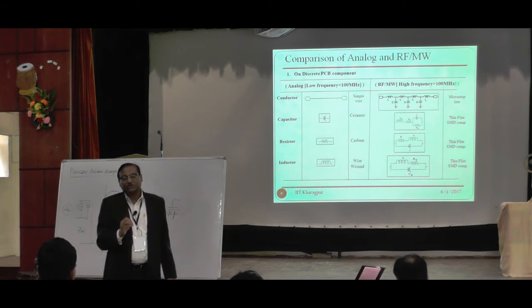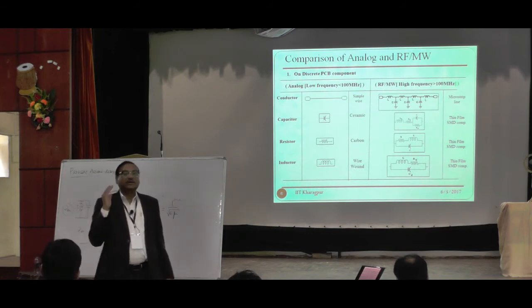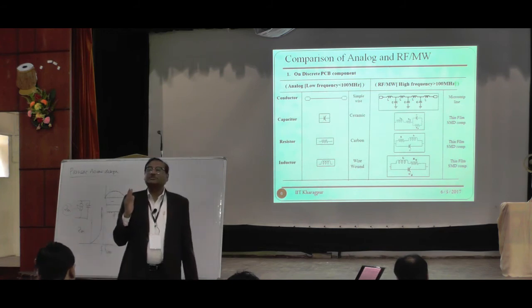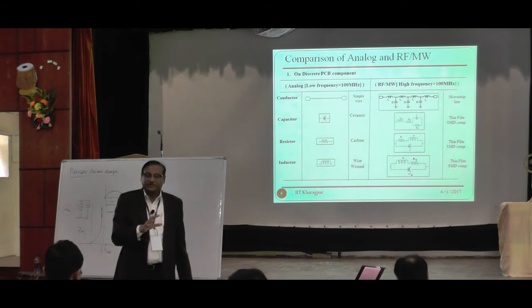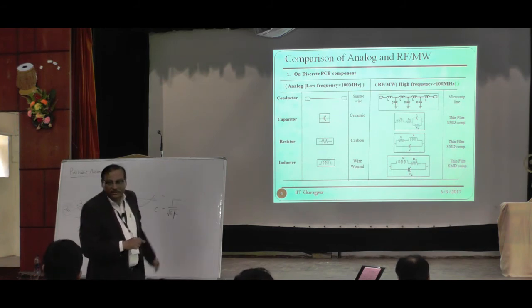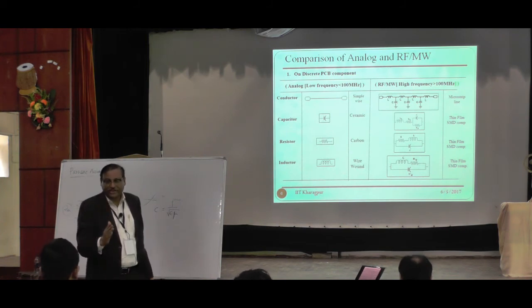You have to find out what is, in case of transistor, what I said, the cutoff frequency. Cutoff frequency means the frequency of unity gain bandwidth. And the self-resonance frequency, just as explained. So those frequencies are the limiting factors. So you should make your operating frequency 4 times or 5 times, if not even 10 times, less than that.